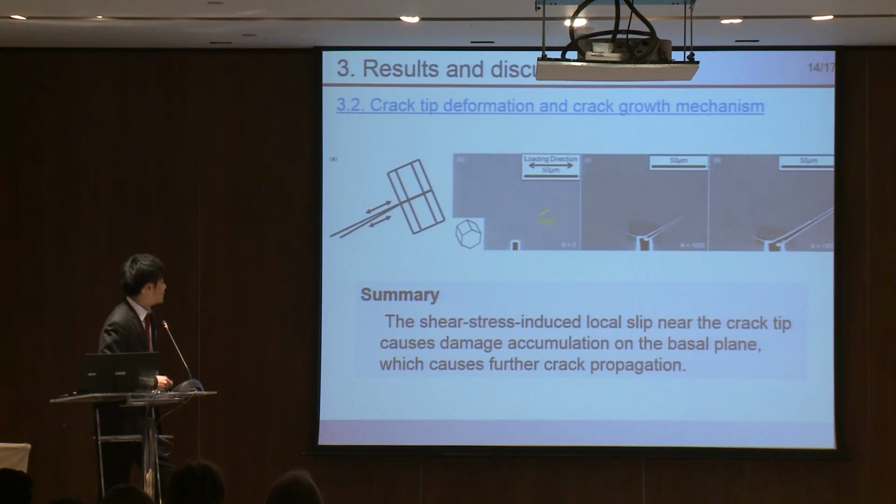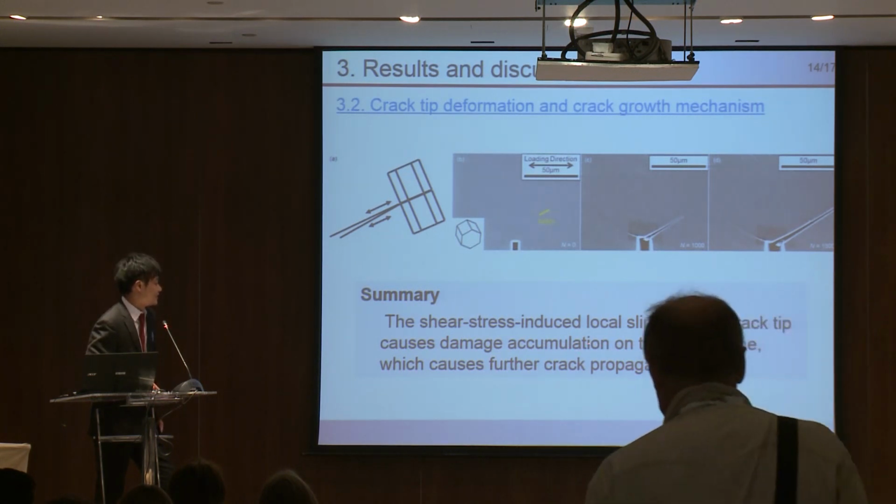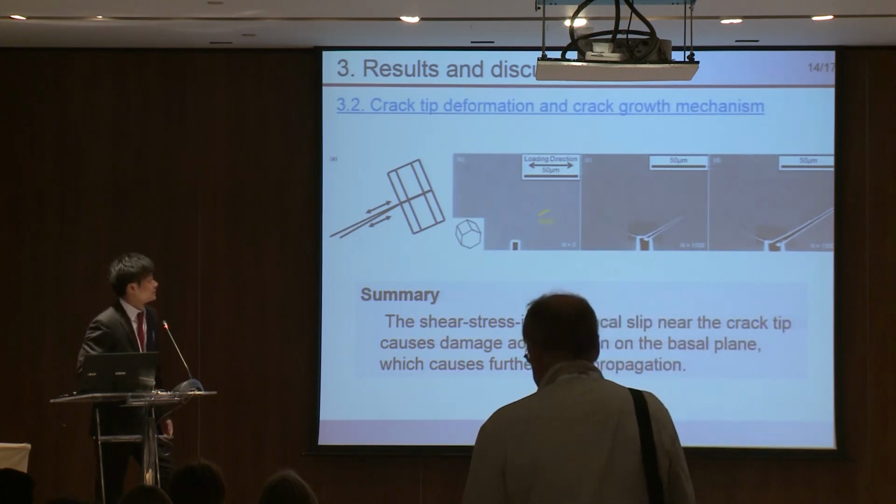So in summary, the shear stress-induced local slip near the crack tip causes damage accumulation on the basal plane, which causes further crack propagation.